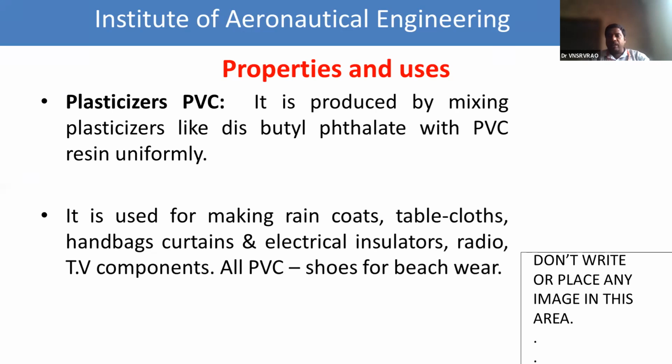The entire application depends upon the nature of the plasticized PVC, because it is manufactured in the presence of plasticizers. Because of the plasticizers, it acquires that molding nature. So this is plasticized PVC, including its applications. Now, everybody understood about PVC?